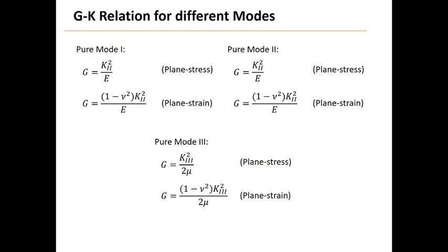Because sometimes we can measure fracture energy more easily, because fracture energy depends on the surface energy if you have a brittle material. So you might want to get the fracture energy without doing a fracture experiment. That's one thing you can do, and then you can convert it to the stress intensity factor. So then it allows you to study a crack problem.